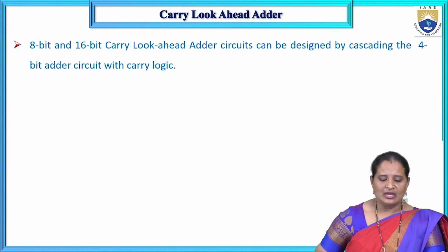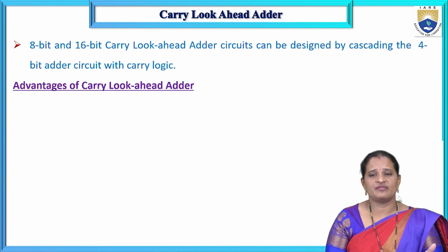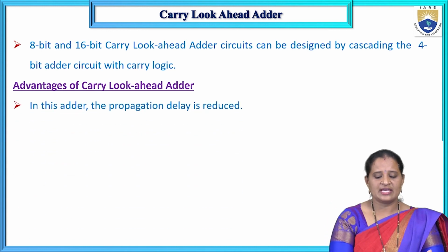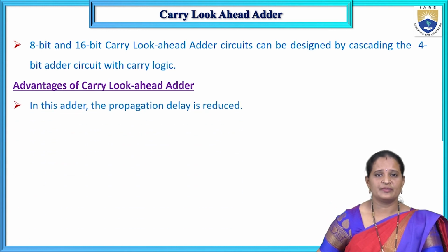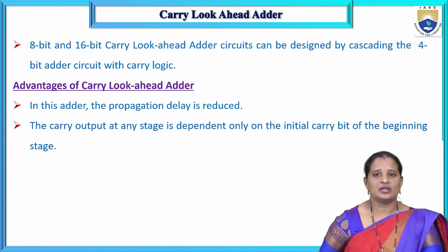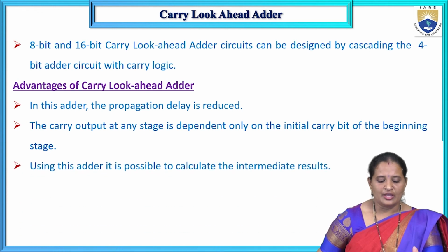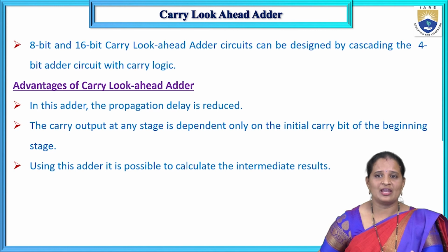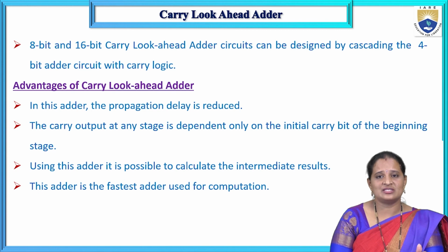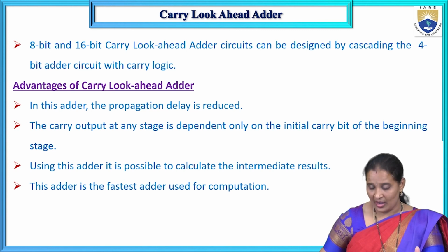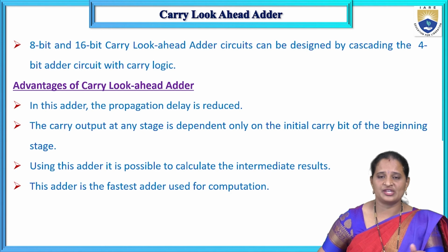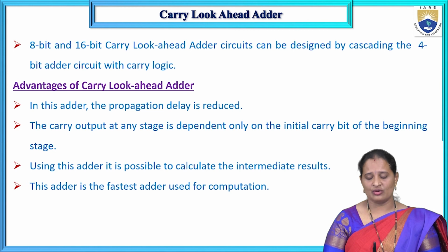Now let us see the advantages of carry look ahead adder. In this adder, the propagation delay is reduced and the carry output at any stage is dependent only on the initial carry bit of the beginning stage. Using this adder, it is possible to calculate the intermediate results also. So this adder is the fastest adder used for computation like addition or subtraction. So this is about a carry look ahead adder.